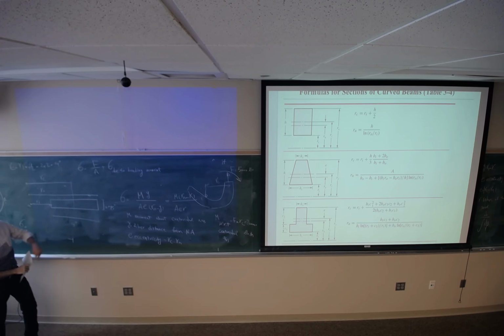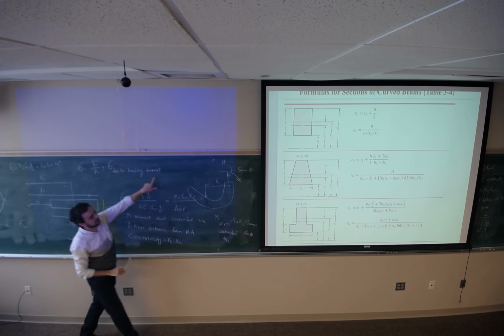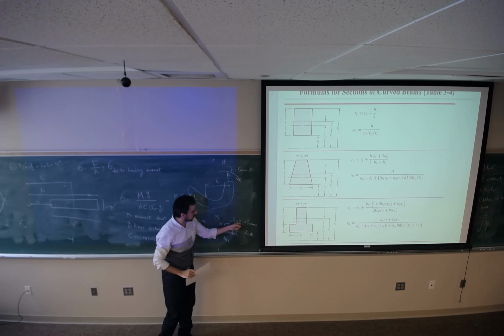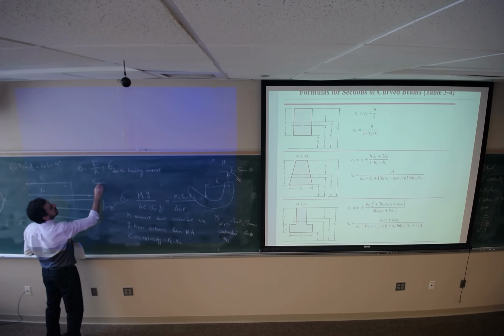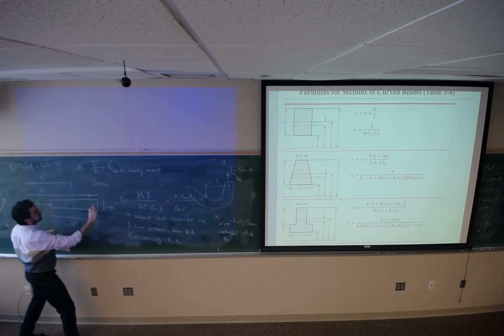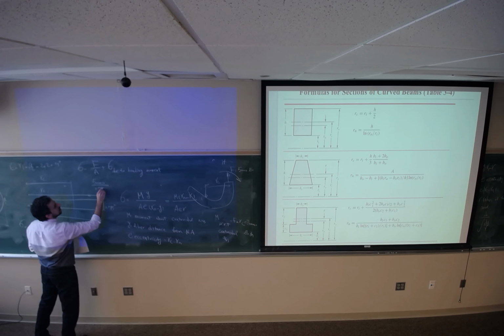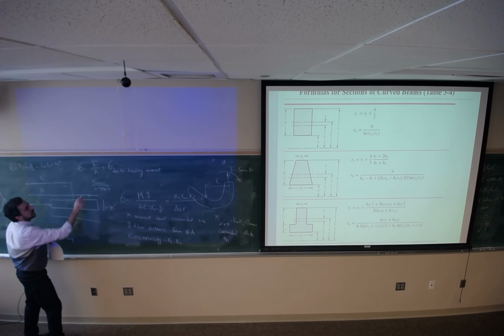This is due to the axial load, this is due to the bending moment, because this cross section is under this moment. F divided by A, 5,000 divided by thickness 0.75 times 4. It's going to give me this.